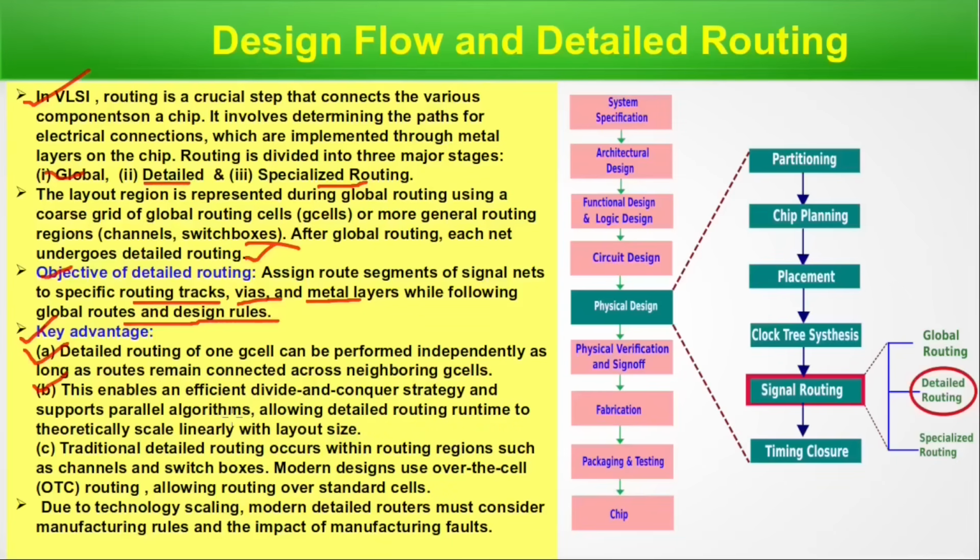If routing on multiple sections of the design runs in parallel, it saves time, allowing detailed routing runtime to theoretically scale linearly with layout size. So the runtime is linearly related to the layout size. If the layout size is big, then runtime is more.